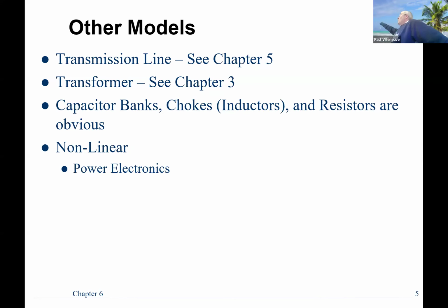You will also see them for communication signals where they act as a line trap. And sometimes you'll see them put into the system at night because you're trying to reduce the voltage. But for the most part, they're pretty limited when you see reactors. Resistors are not that common either because, again, it's wasting energy. So why would you put something on the system that you're not getting paid for? You do see resistors on neutrals in many cases, or sometimes load banks with resistors, but capacitor banks way more often than any of the other ones.